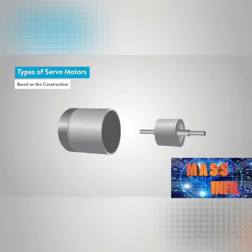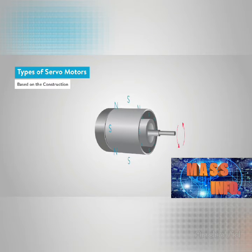When the stator field is excited with voltage, the rotor follows the rotating magnetic field of the stator at the same speed, or synchronized with the excited field of the stator. And this is where the synchronous type is derived. With this permanent magnet rotor, no rotor current is required. So when the stator field de-energizes and stops, the rotor also stops.